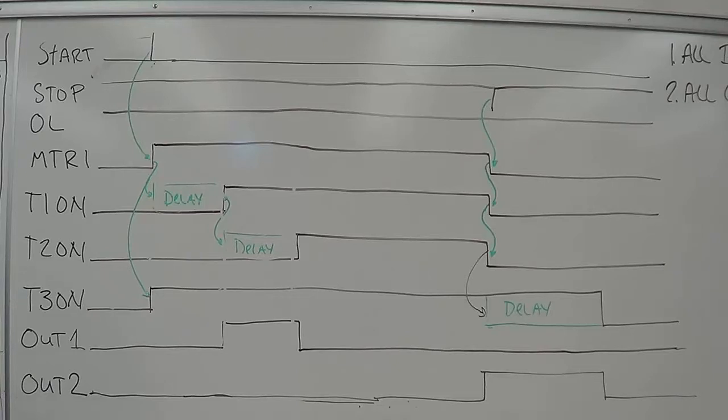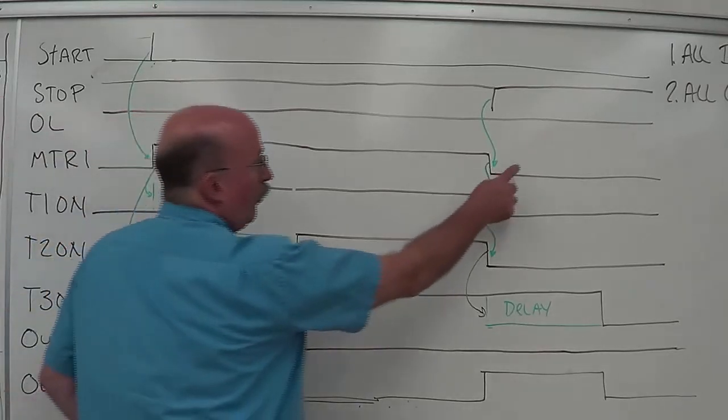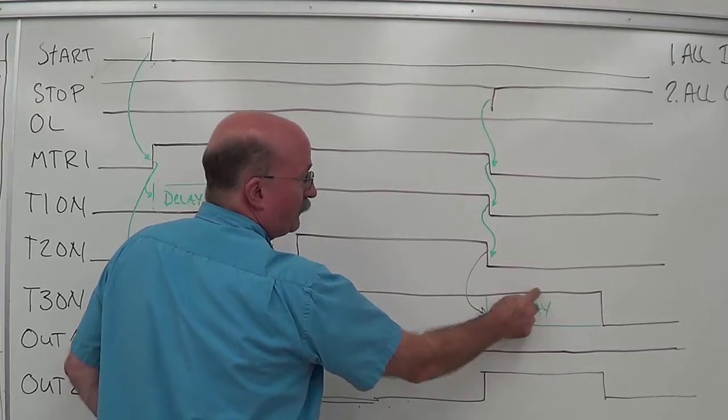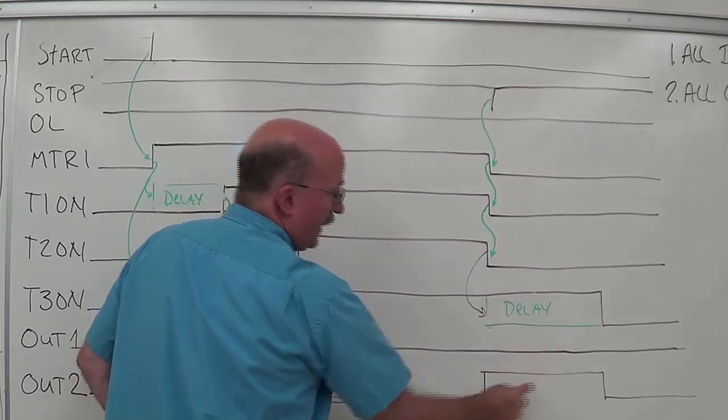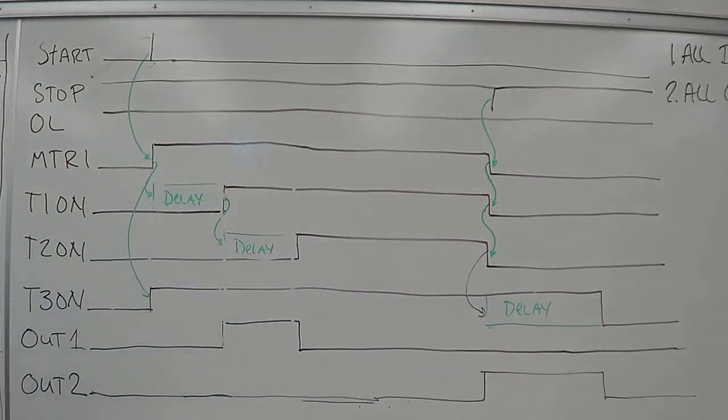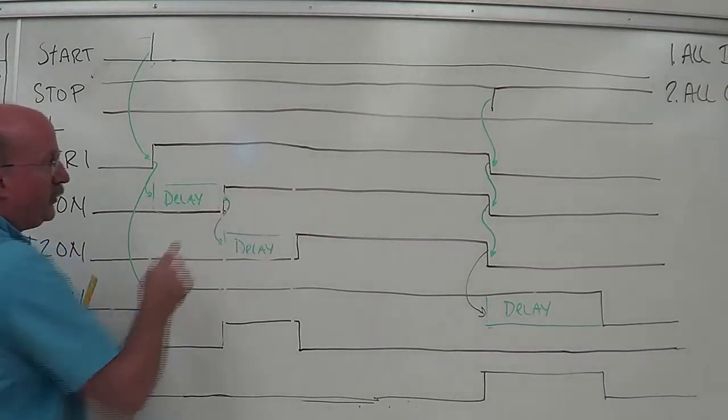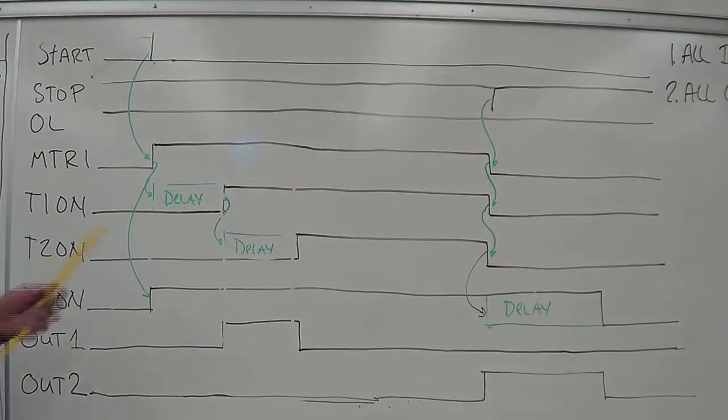Okay. Now over here, motor 1 is off. This off delay is still on, so that means that output is on. So if a coil or an input is off, that goes to a normally closed contact, because the input's not being energized. Normally closed contacts are closed, so they allow power flow through them. If the coil is on, like this one over here, you'll use a normally open contact, so when this is energized, those contacts are closed and allow power flow to go through.